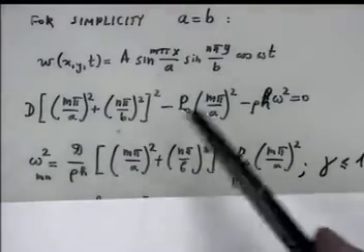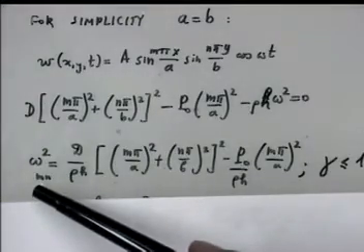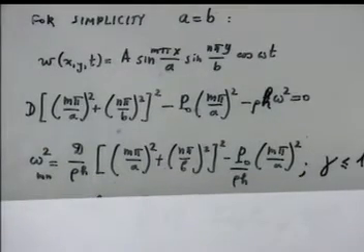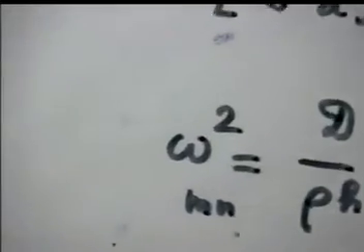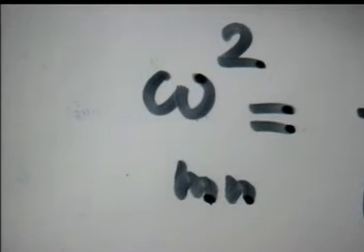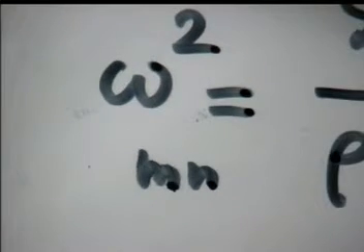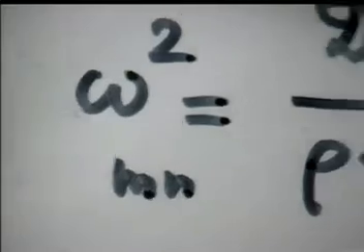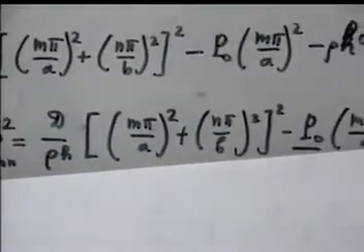But because this omega depends upon m and n, it makes sense to give an index mn. Sometimes we want to magnify, like we put magnifying glasses. If you don't see something in the book, you put a magnifying glass and look at what happens there. So omega sub mn. There are many, many natural frequencies, infinite actually, because m goes from 1 to infinity, n goes from 1 to infinity. So it is infinite times infinity, a lot of natural frequencies. And that is this expression.